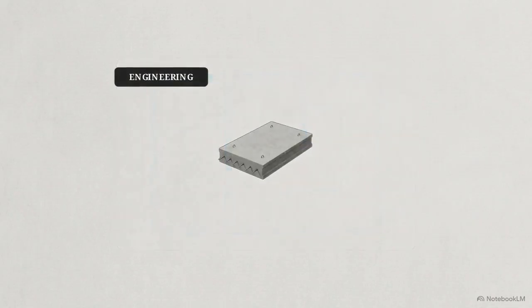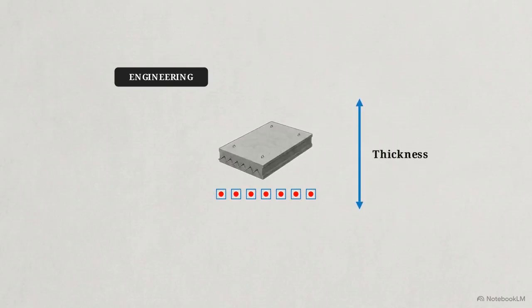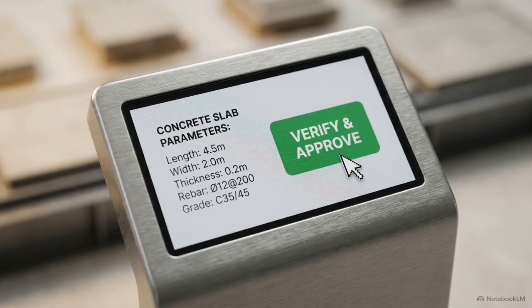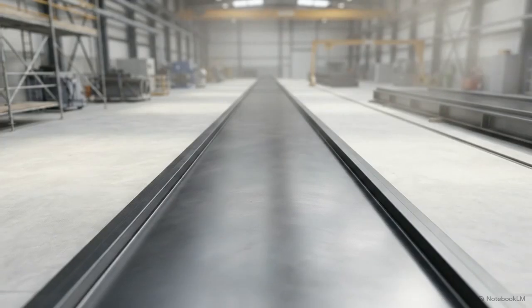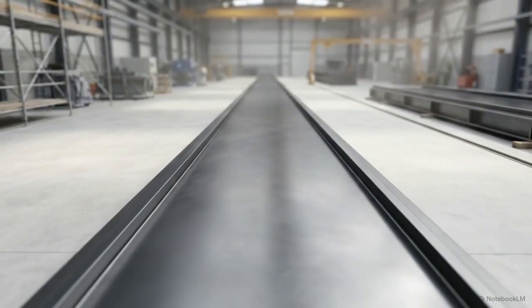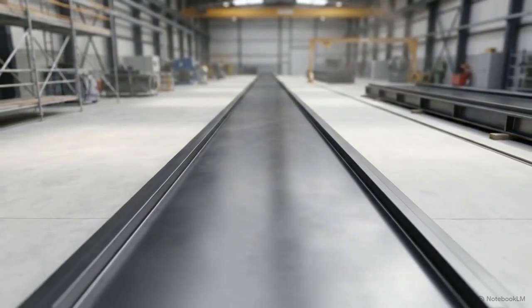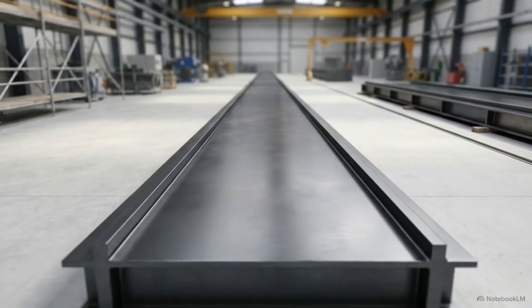It then analyzes the applied loads and span limitations to design the panels, confirming exact slab thicknesses and cross-referencing proprietary strand patterns. This entire output operates with mandatory human-in-the-loop verification before the data proceeds. Once the digital layout is verified, the challenge shifts to the physical floor. The constraints are unforgiving, managing multiple casting beds that are typically 100 meters long by 1.2 meters wide.